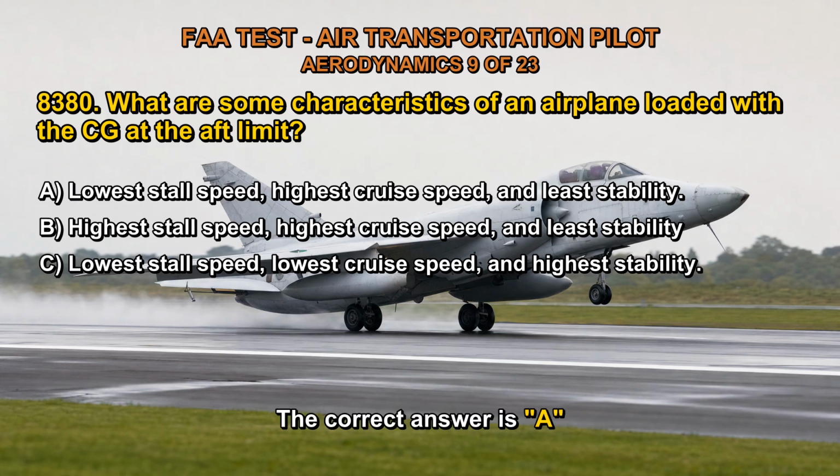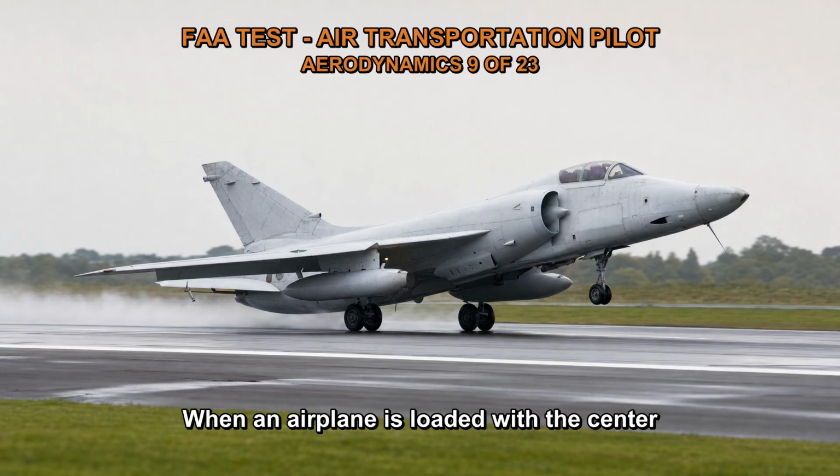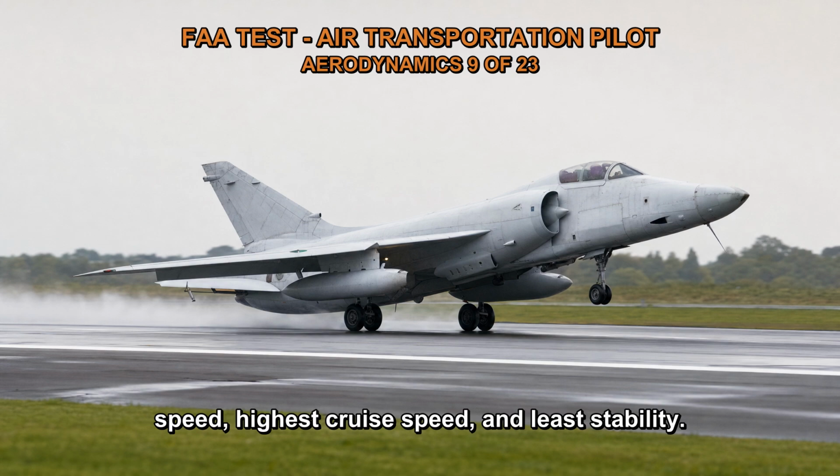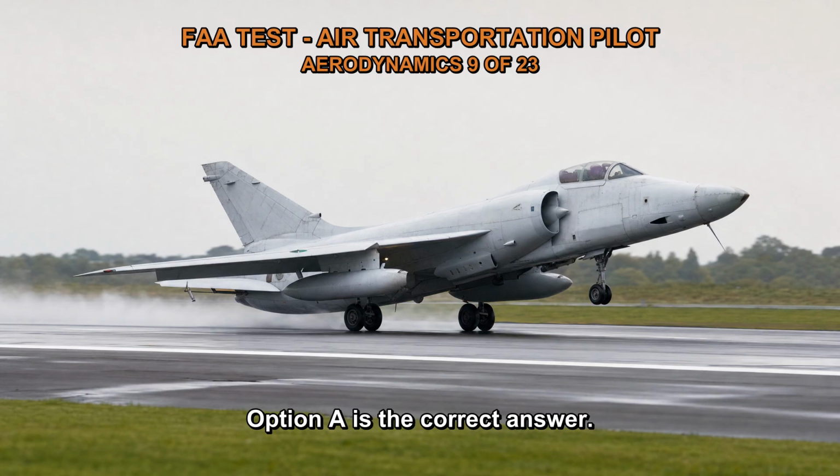The correct answer is A. When an airplane is loaded with the center of gravity, CG, at the aft limit, it typically exhibits the characteristics of the lowest stall speed, highest cruise speed, and least stability. Option A is the correct answer.